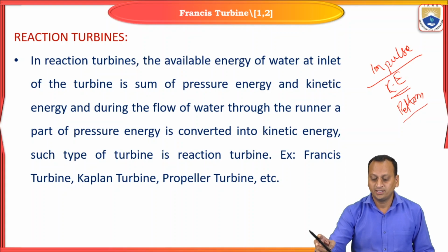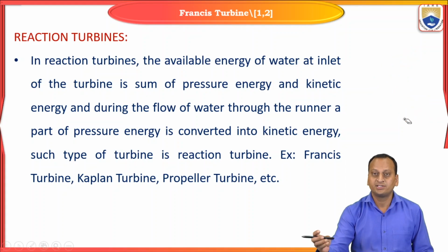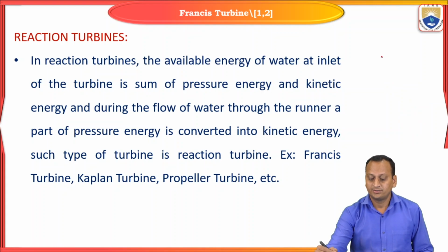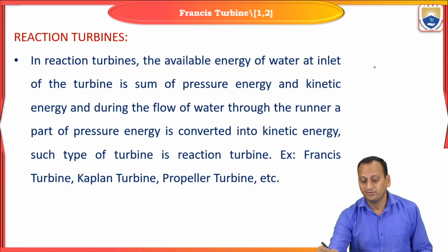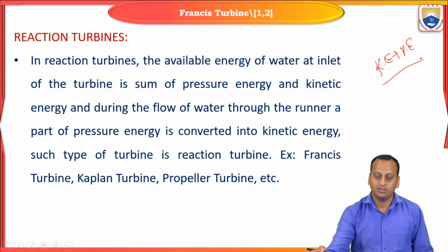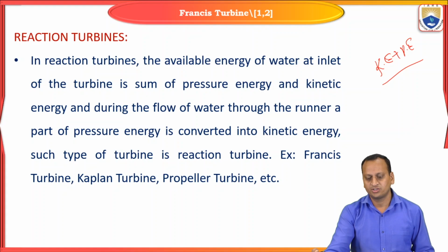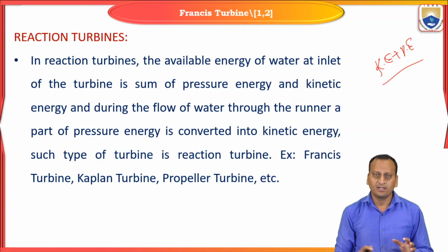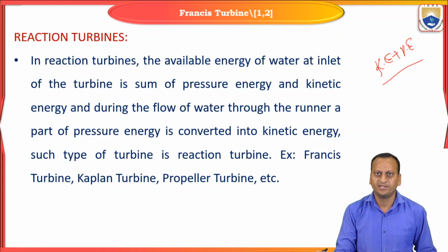Similarly, a reaction turbine is one where both kinetic energy and pressure energy are available at the inlet of the runner. In this reaction turbine, before entering the turbine, the pressure will be high and the kinetic energy will be small. The substantial energy remains as pressure energy, and only a partial energy remains as kinetic energy.